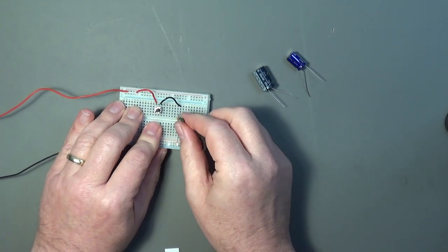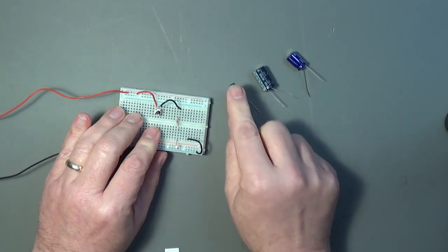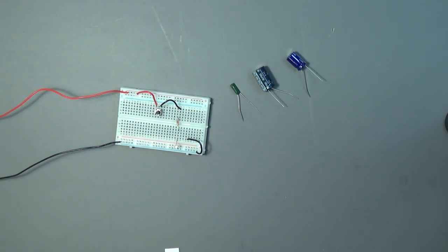This ability to store electricity is used a fair bit for capacitors in various ways, like for timing circuits. And a very important use that we use them for today, in the modern era, is that we use them as computer memories. So your dynamic RAM is just millions and millions and millions of microscopic little capacitors all connected together with logic that remember everything in our computers these days. So that's the storing electricity part of capacitors.